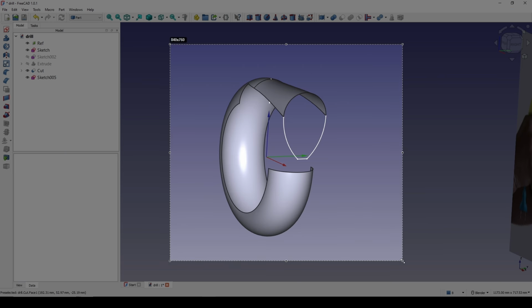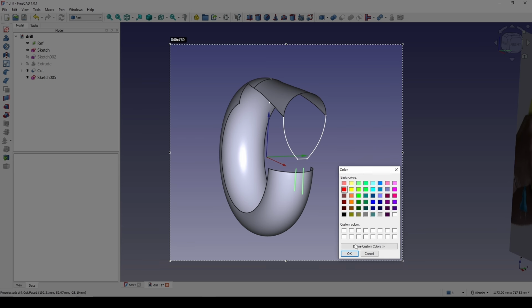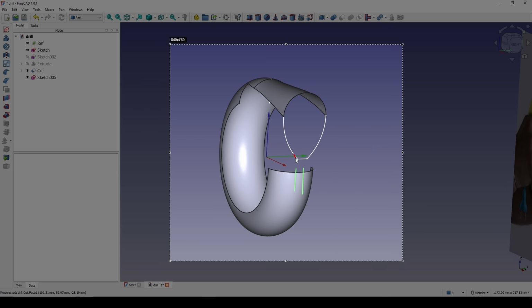The next step is I want to create 2 lines to separate this one to have 2 lines like this. And when I have these 2 lines, I will use the blend curve to connect in between like this. Connect in between of these. And from there, I will fill this surface. Okay.